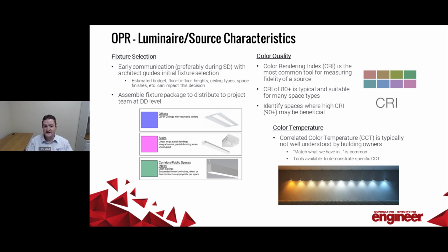And there are a lot of benefits that you can get by moving to a higher CRI. I mentioned earlier, I'm in healthcare, do a lot of healthcare engineering. I don't put any light in a healthcare space that is not 90 CRI. And just the benefits of being able to get the really true to life color rendering so that a physician can look at your skin tone or your eyes or whatever they're looking at, even discrimination between two different pill types. Maybe you have a pink pill and a maroon pill and they're kind of the same. You need to be able to tell the difference so that you don't misapply those things. So that high CRI, healthcare is one example.